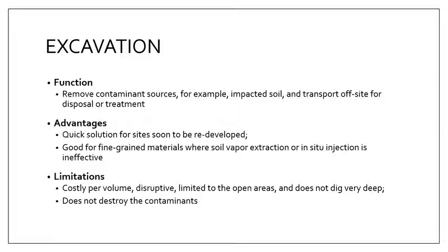You can't really dig beneath a building. Also, the method does not dig very deep. Typically, if you're talking about manual excavation using human labor, it doesn't go beyond 1 meter. And if you're using a backhoe, it doesn't go beyond 4 or 5 meters. There are other methods like deep or large diameter borings, but first they can get expensive quite fast. Another limitation of the excavation method is that it doesn't destroy the contaminants.